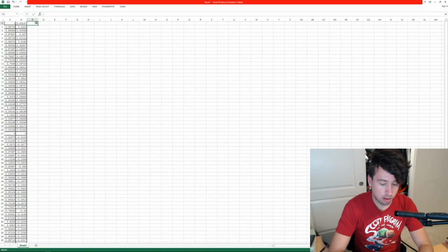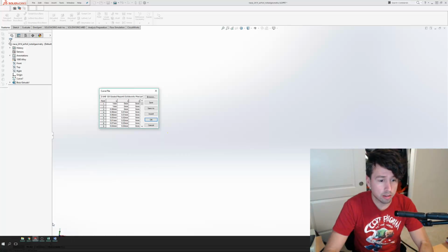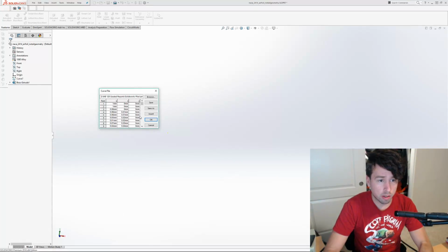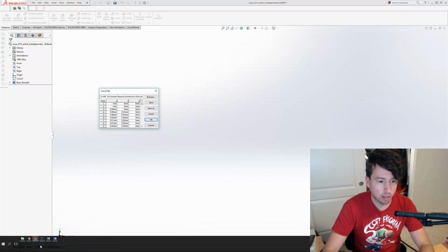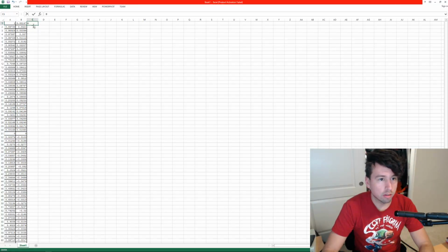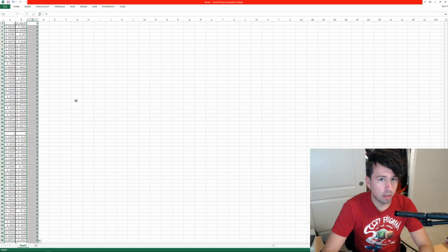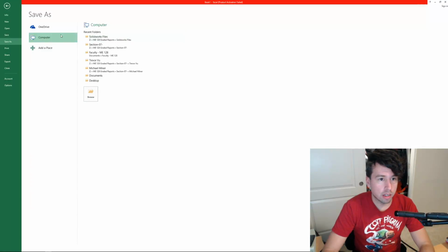Isn't too bad. Now the one thing you need to keep in mind is that in SolidWorks, it wants a Z coordinate, so for thickness. We don't really care about thickness at this point. That's for 3D curves. So you'll just insert a 0 column, the same number of rows. That's what you have.